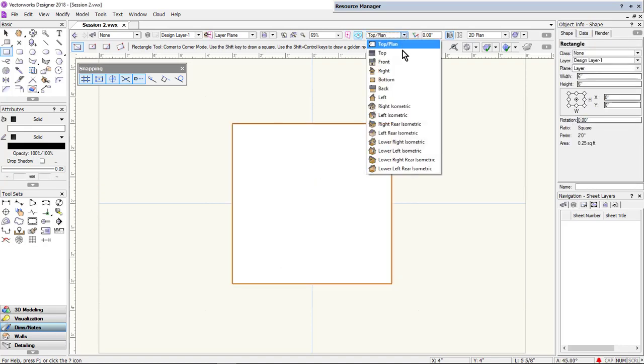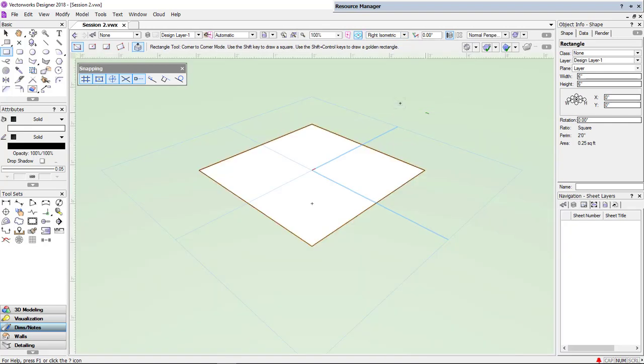So that's created a rectangle. If I go up here and I change to an isometric view, you can see there's my rectangle. But the other curious thing is that there's now a new mode on my toolbar, the push-pull mode. With this mode activated, which it is by default, I can go to the rectangle I've already created, I can click and I can pull that up. Now I'd like to come back and look at that because what I'd like to show you is what's happening.